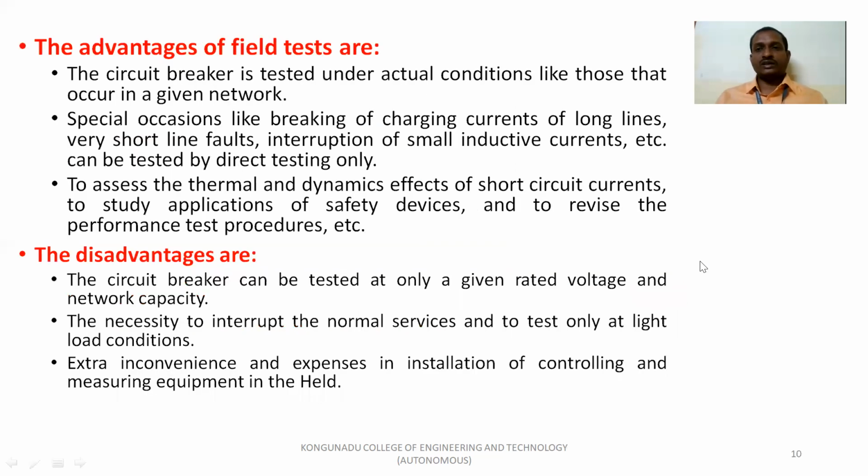So, advantages of the field test. If you test the circuit breaker directly in the field, we have these advantages. The circuit breaker is tested under actual conditions like those that occur in a given area. Second, special occasions like breaking of charging currents of long lines, very short line faults, interruption of small inductive currents, etc. can be tested by direct testing only.